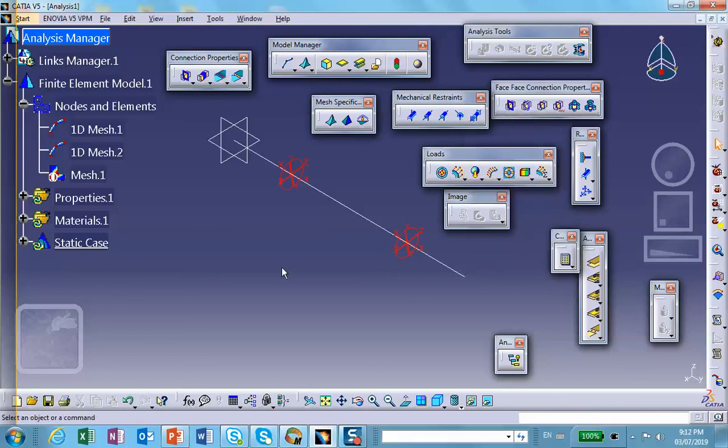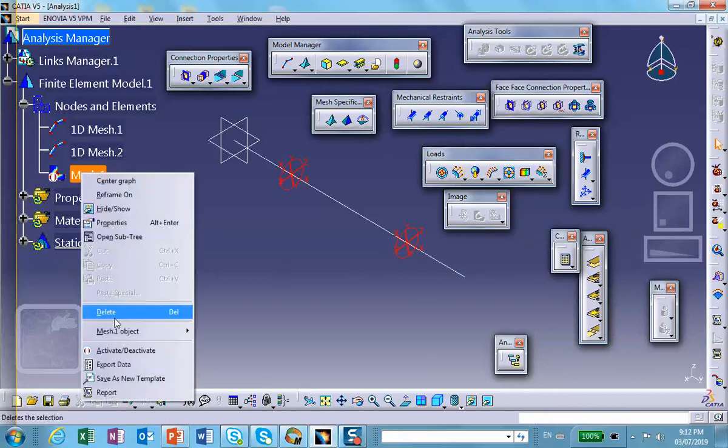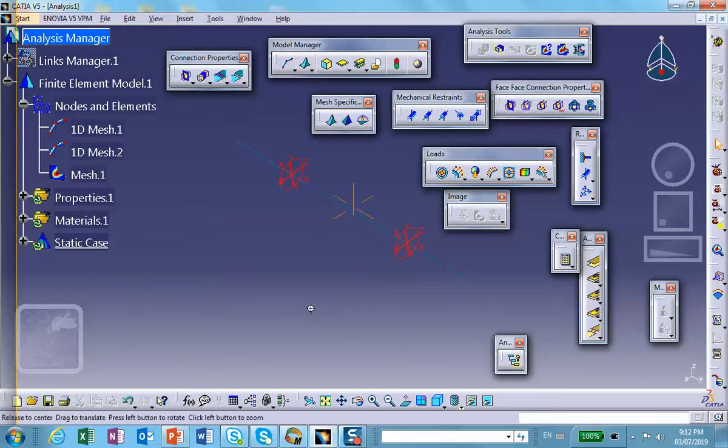Let me show you the mesh one more time. So activate the mesh. What I want to show you is that at the interface, there are two different nodes. So on this side, node number 8. On the other side, node number 1. So somehow I have to tell the software later on that node number 1 from the left side is the same as node number 8 from the right side. Okay? All right, so let me deactivate this. Deactivate this for a second.